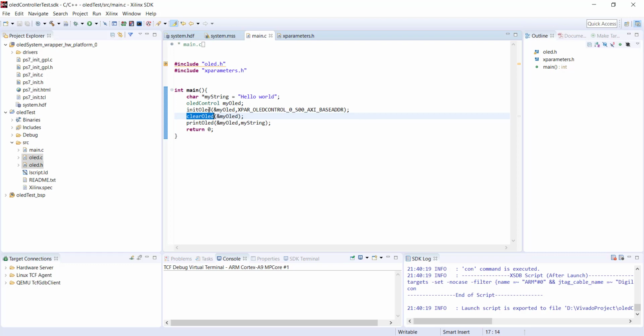So your init function will basically send all those initialization sequences to the SPI controller. Then it gets initialized. Then you will again send the command for setting the page address, column address, etc. Then you send the actual data. That's also possible. So in that case, you won't have the OLED controller in hardware, that is more or less completely in software, but you will have only the SPI controller in hardware.